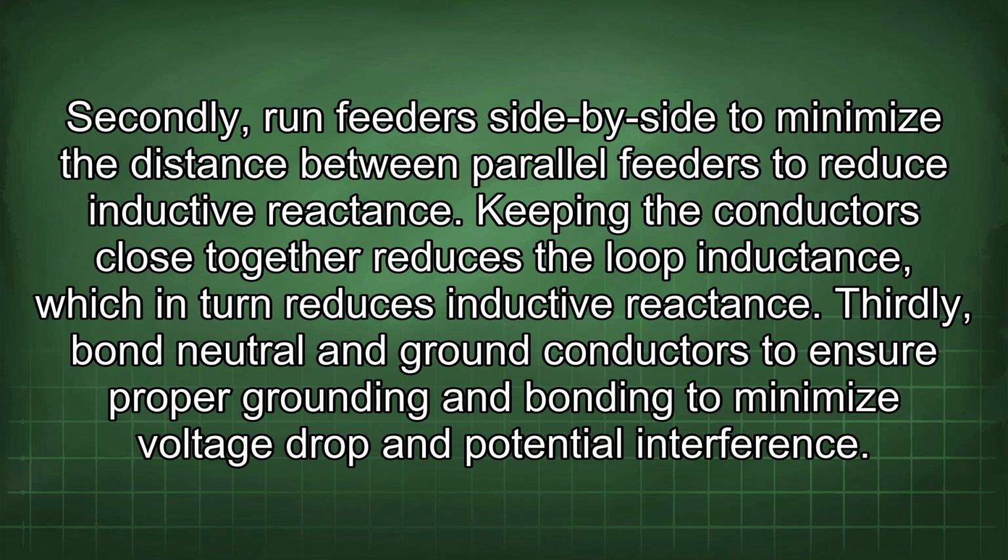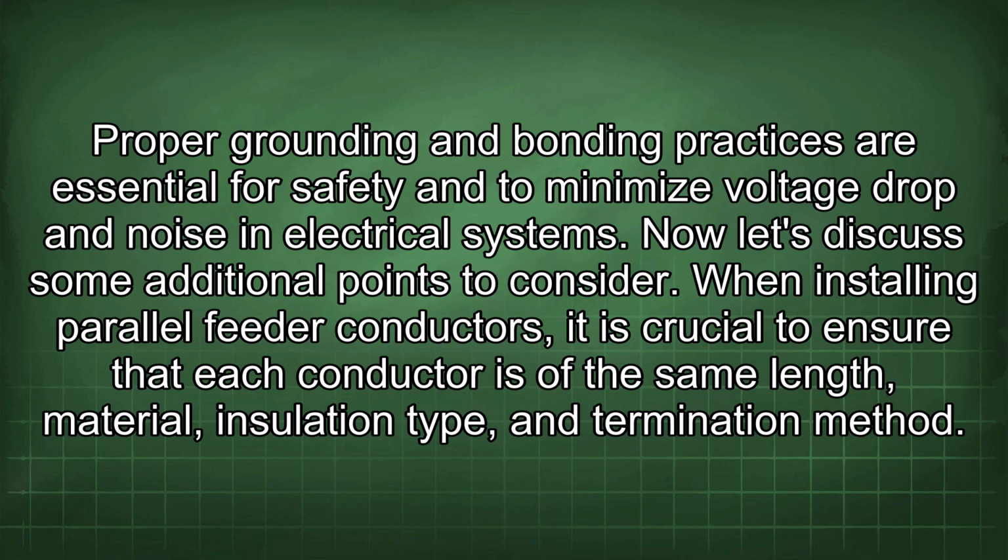Thirdly, bond neutral and ground conductors to ensure proper grounding and bonding to minimize voltage drop and potential interference. Proper grounding and bonding practices are essential for safety and to minimize voltage drop and noise in electrical systems. Now let's discuss some additional points to consider.